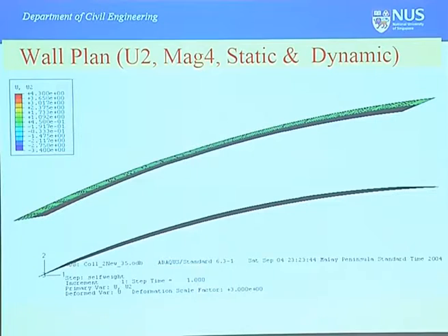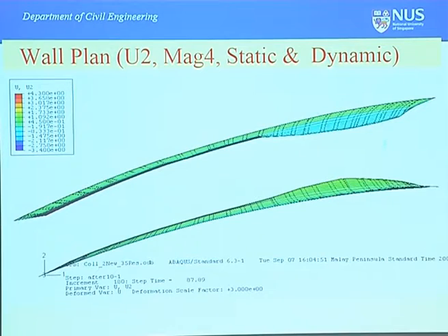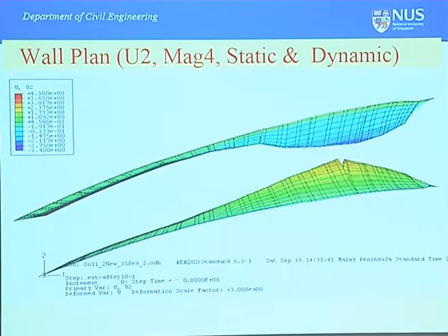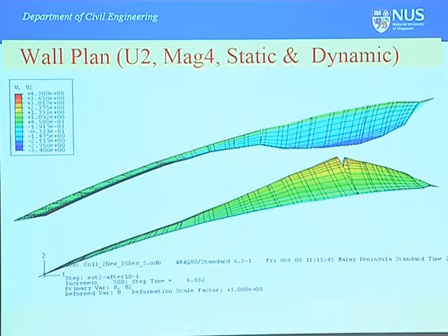Now I'm going to see whether we can animate this thing. Here we can see an aerial view of the south wall and the north wall deflecting in. This is an aerial view of the deflection. This is the section that collapsed. This is the circular shaft. Can you see the split here? This is no accident. We actually modeled that, allowed it to split, and it actually split up. You can see the split happening over here. This is the original split, and this is a secondary split because the curvature here is so large, it just broke the wall there. So this is the situation.